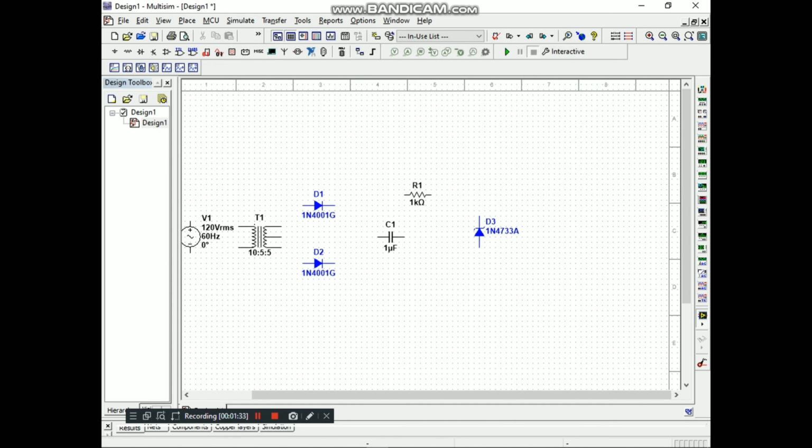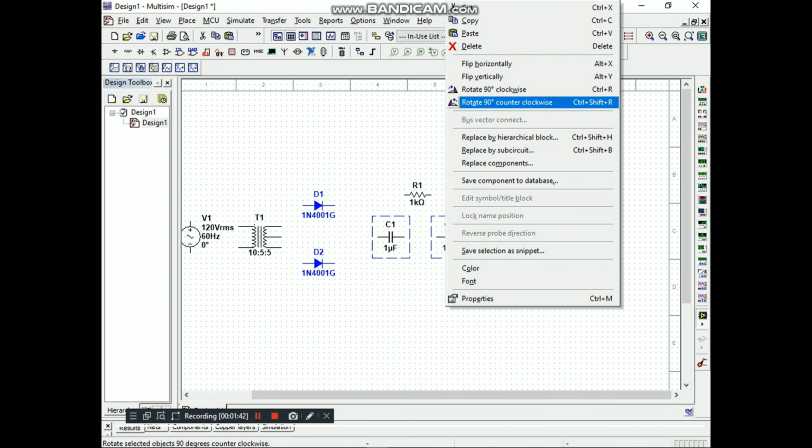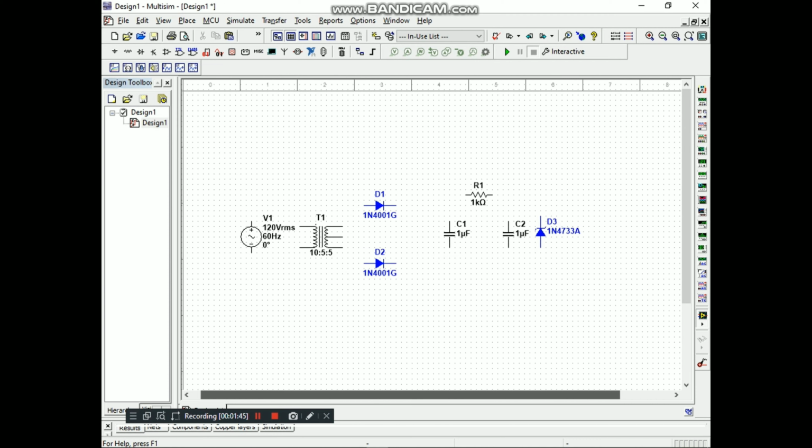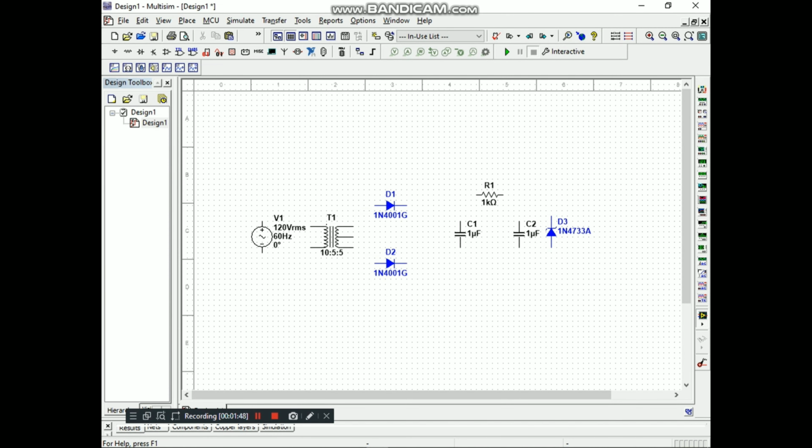The rectifier circuit converts the incoming AC to DC, but unluckily, it does not make it a pure DC. The output of a rectifier is pulsating DC and is not considered good to power up sensitive devices. The rectified DC is not very clean and has ripples, so we need a capacitor filter to convert the pulsating DC into pure DC, or to remove distortion from the signal.